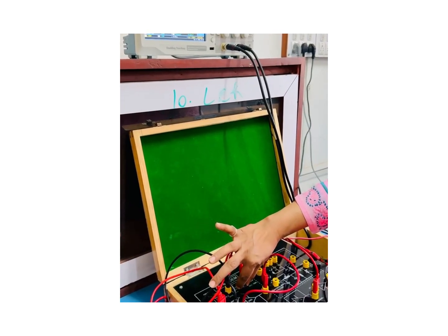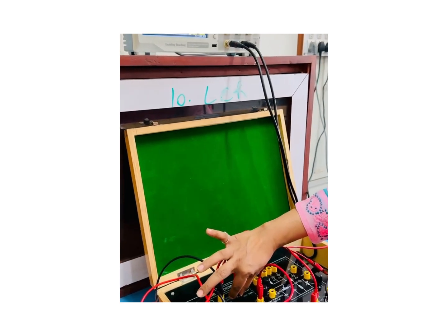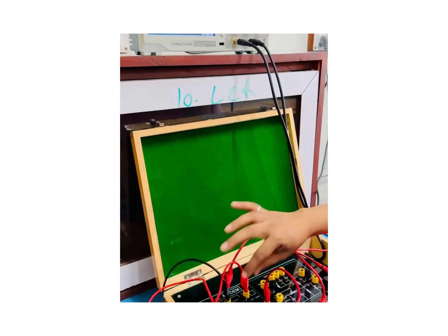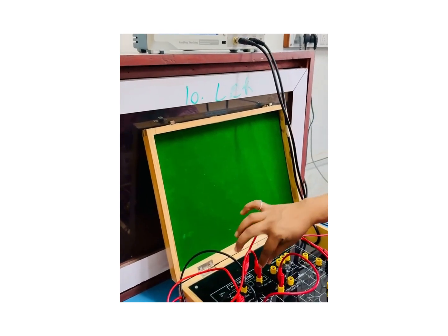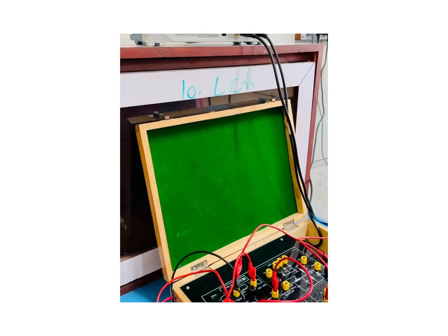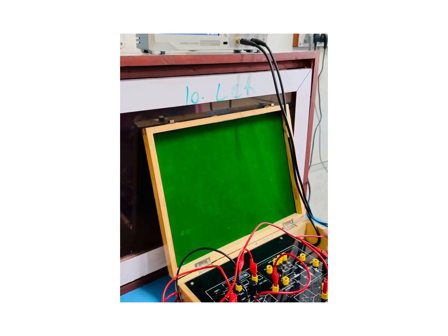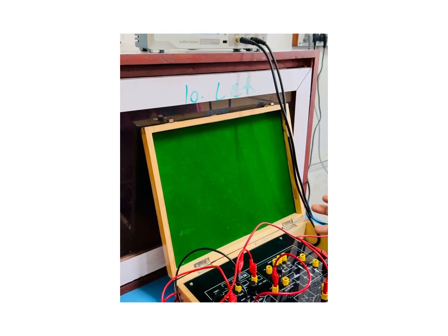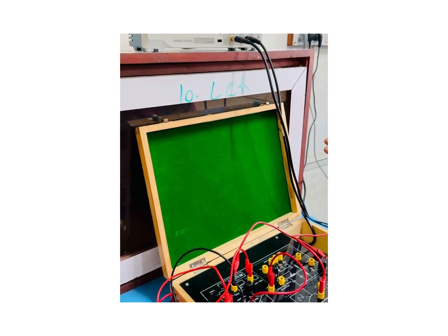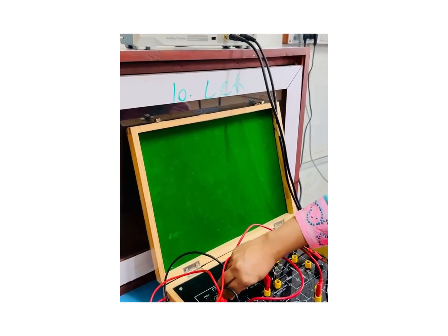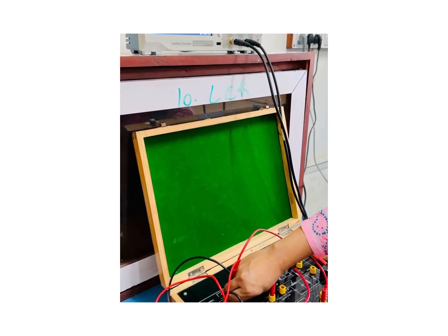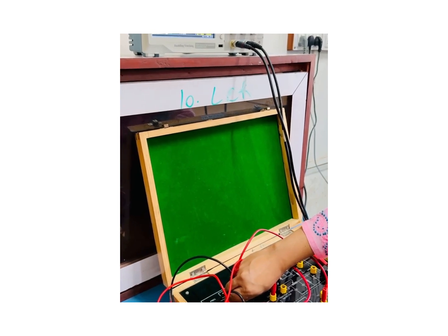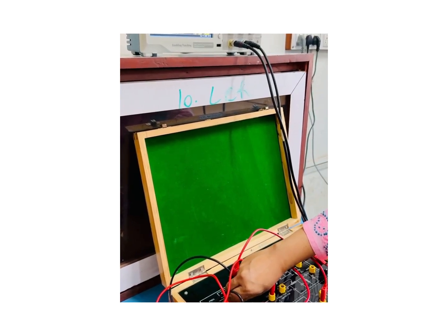So modulation index decides the depth of modulation, and whether the demodulated signal can be generated without distortion is dependent on the value of modulation index. Ideally, the modulation index is set between 0 to 1, but as we go on increasing the modulation index more than or above 1, we will find that there will be distortions in the modulated signal and the reconstructed signal will also be seen to have the distortions.